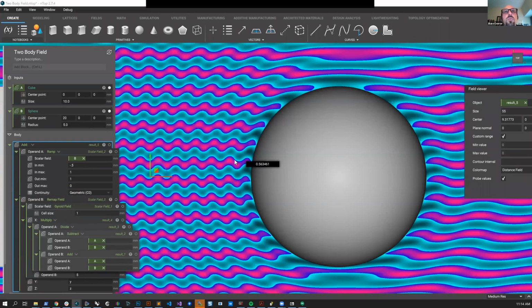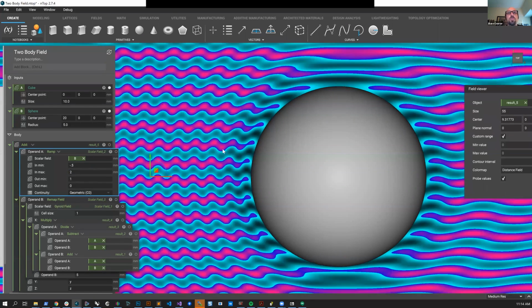And you can see we've created this gorgeous field of nozzles, and they all have the same kind of leading edge. We've gone skew because our axes of the remap are no longer perpendicular here, but you can see every little one of these nozzles is dressing the body in the same way. And if we are engineering a heat exchanger and we have some parameters over how we want to change the pressure in our convergent nozzle here, you have that control. You can say, actually, let's give the fluid a little bit more space to compact. And you're really engineering an interface that also has controllable fluid properties. So that's pretty neat.